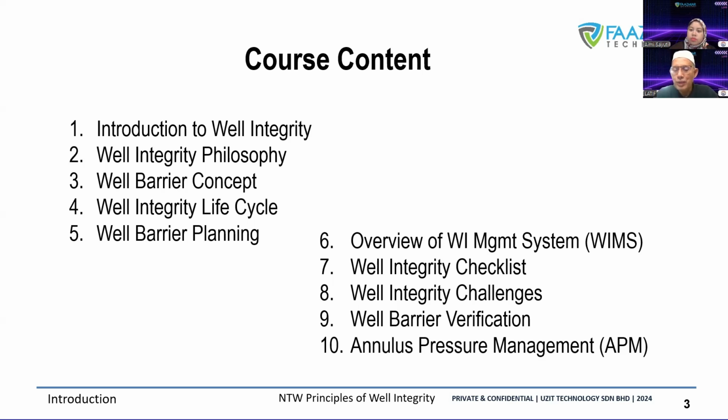Verification, normally we have a barrier. Whenever you reinstall or whenever you have a failure, you have to reinstall the barrier and you have to verify. So we need to understand what the different requirements for verification are. And of course, in oil and gas, we find that verification is not easy because we have limitations of facilities, and we are not able to have something too long to do some verification, because it will involve shutting down the well for too long, or maybe we have to pay extra cost for the service provider that provides the repair job. So it is going to be quite costly if it is too long. So verification has to be done as soon as possible, and we try to avoid a very lengthy process.